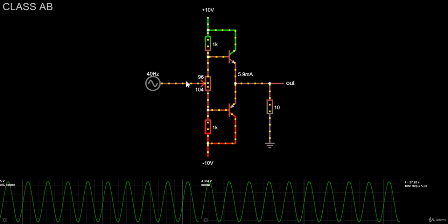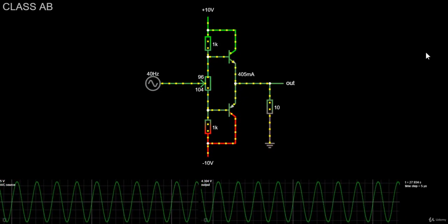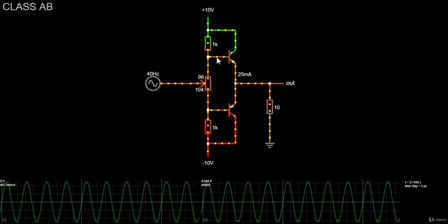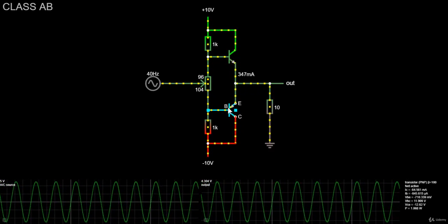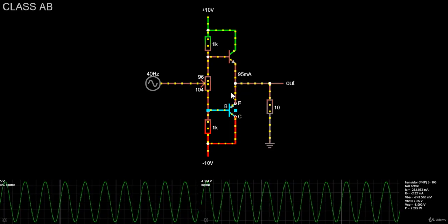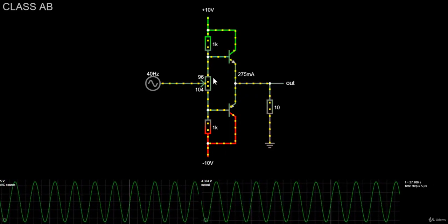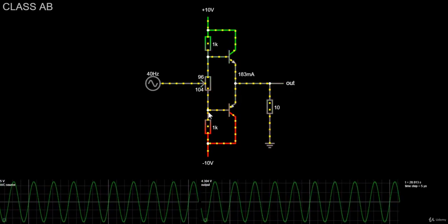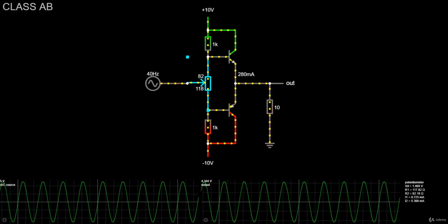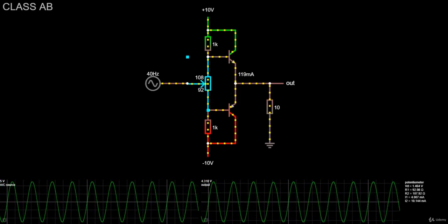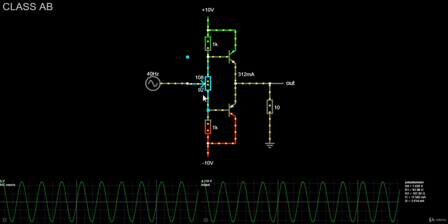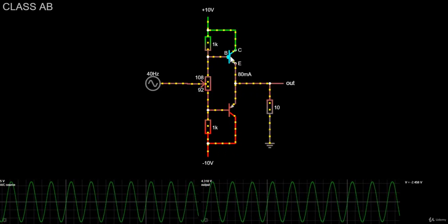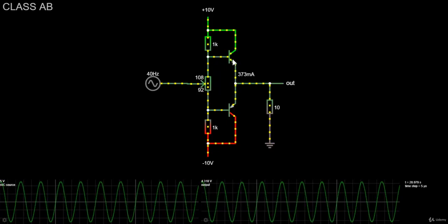So again, the advantage of this adjustable biasing arrangement is that the basic amplifier circuit does not require the use of complementary transistors with closely matched electrical characteristics, or an exact resistor ratio within the voltage divider network, as the potentiometer can be adjusted to compensate. So this is the solution to the problem of having slightly different electrical characteristics of the two active devices.